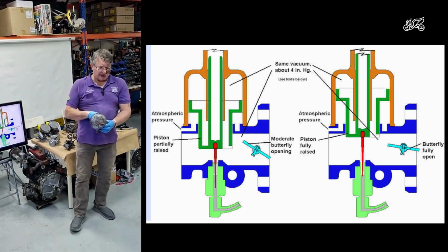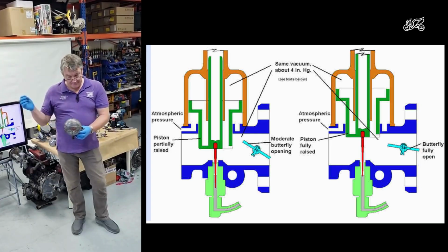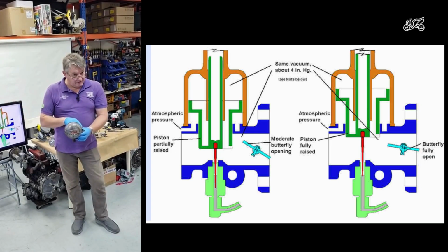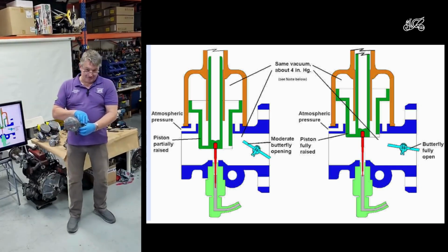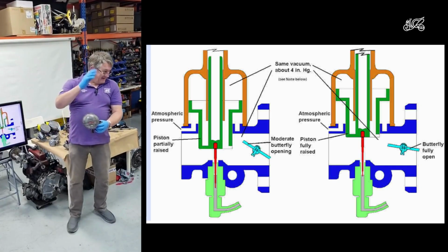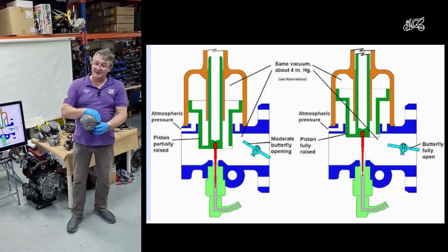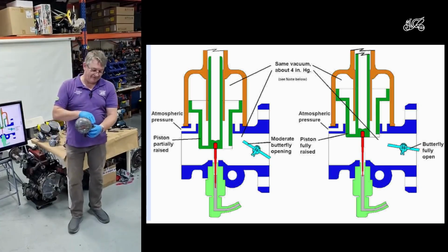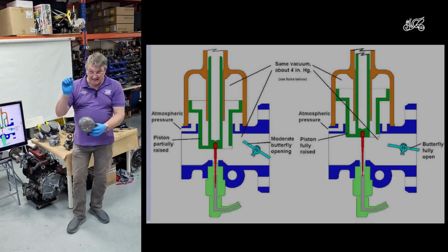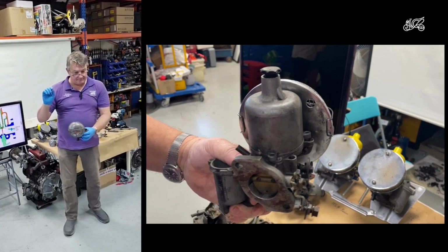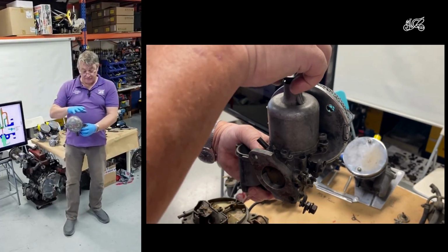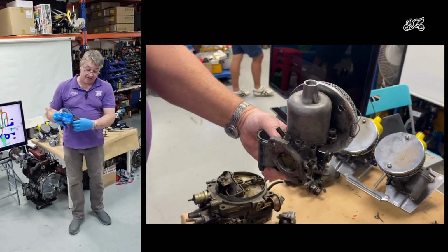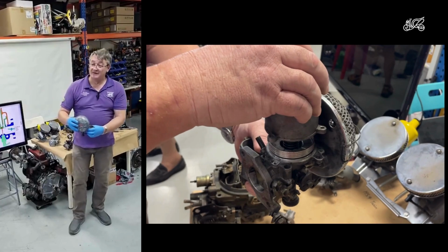And these types of carburetors do suffer from that same debris problem. There's a little needle valve. It's a little bit like a toilet cistern. So it's basically a float and a valve, and it fills up whenever the level drops. But that little valve can get debris on it and stick, and then it will overflow. And normally you see the overflow just running down here. Yeah.